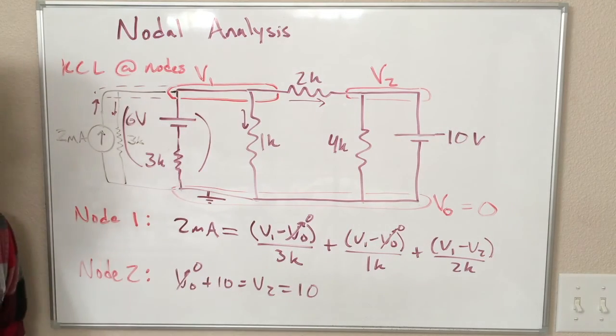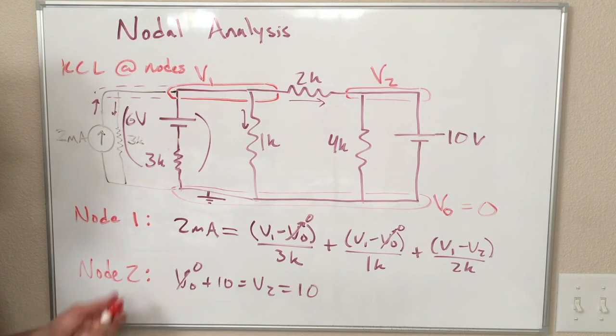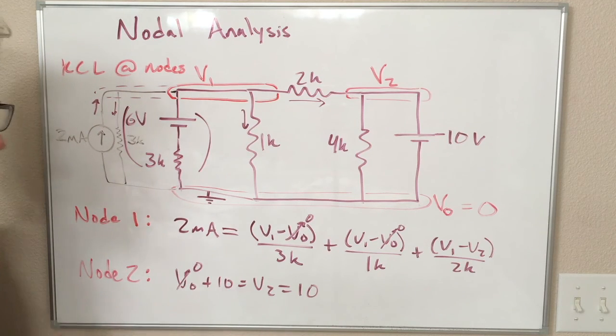All right, so nodal analysis, also useful. If you're gonna apply these techniques by hand, it's really just whatever you're the most comfortable with. I'm kind of a branch current analysis person, or more realistically, blindly applying the voltage law or the current law to chip away at the problem. That's what I do when I don't really have a plan of attack.